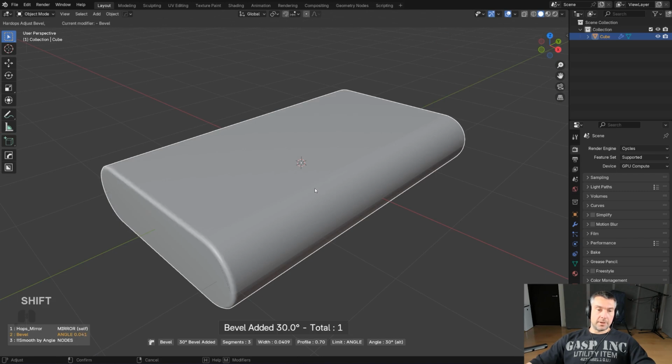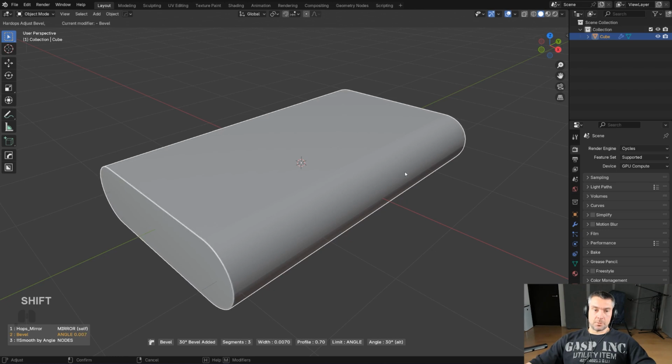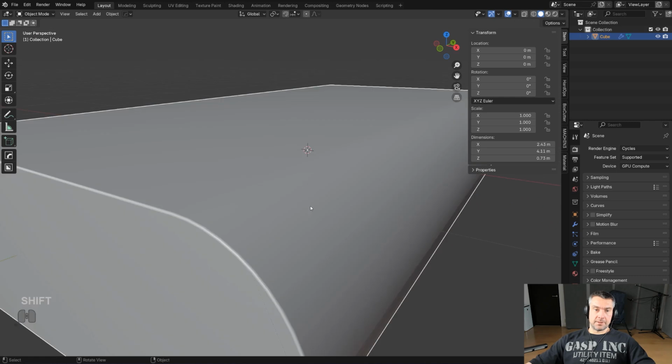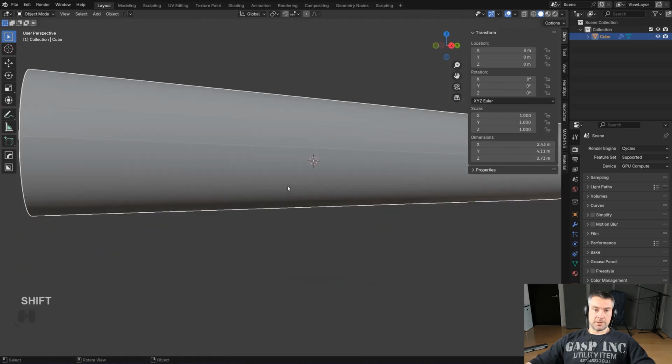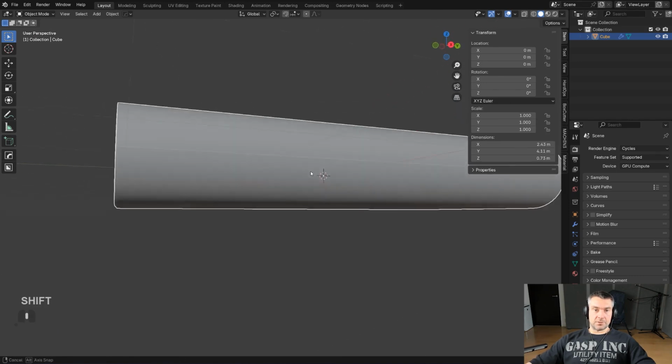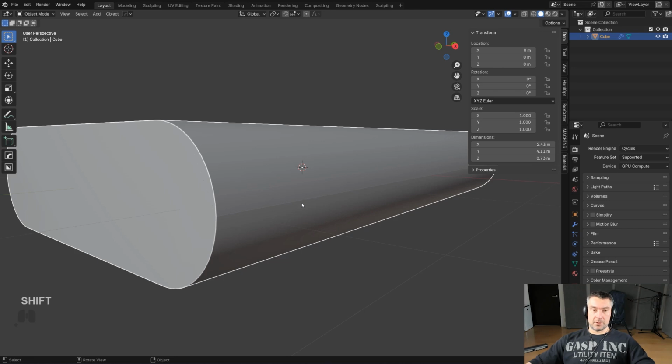Now, when you're adding bevels, you wanna make sure that you know what you're doing. In this case, we wanna add a tiny bevel because it's gonna be kind of like a machined piece, okay? So we wanna add a really tiny bevel to emphasize this kind of metallic, machined nature of this object. All right, now you can see here we have this nasty edge going on the side. That happens when you create a bevel with bevel overlap.